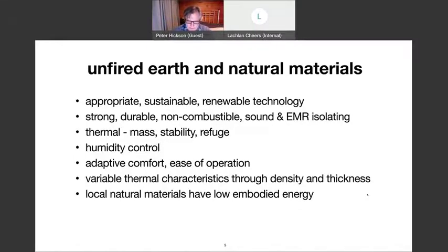By climate, I mean external conditions, including maximum and minimum external temperatures, the seasonal temperature differentials between inside and outside, including diurnal fluctuation and solar gain potential. Climate determines whether bulk, reflective, or dynamic optimized mass insulation is required and where it is necessary and beneficial.